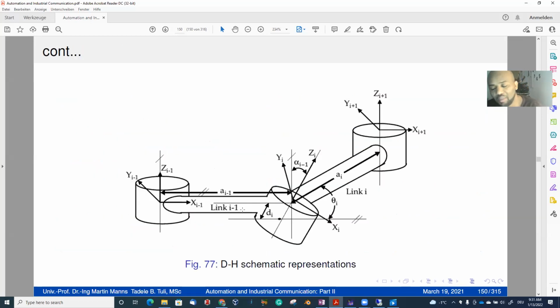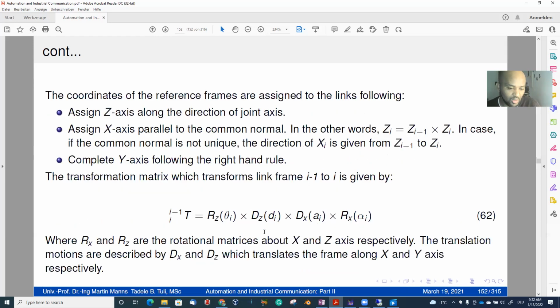But it is a matter of the order of multiplication, because it is a matrix. In matrix, what you do really matters, right? Which one do you multiply first? Which one do you multiply second? If you multiply first this and this, then in the next step, you have to do this and this. This is a procedural difference, okay, between the Denavit-Hartenberg classical and the previous approach.